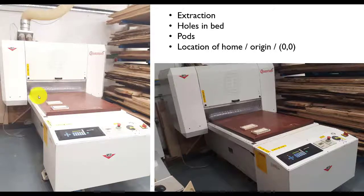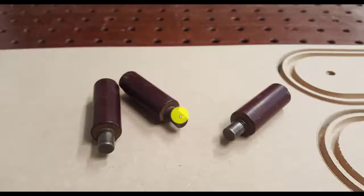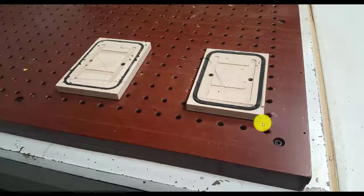So it's just a matter of offsetting the piece over the length of the bed, and the width of the bed should be the same anyway. So rather than starting at 0, 0, we just reverse it and we move the program a set, known distance over to this corner. These little connectors, or these positioners I should say, if I go back for a second, you want to make sure that it's precisely located at the corner. I suppose the de facto 0, 0 is going to be this point at the corner. So we're going to put a couple of those pins into these holes at the side. You'll see that in the video as well.